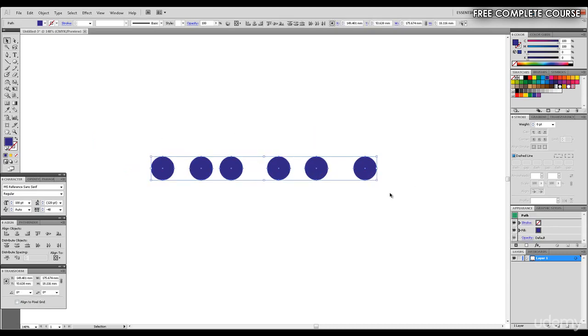And I'm going to highlight all circles, and I'm going to click on this icon beneath Align Objects. Clicking upon that, you'll see that all of the circles have been aligned one on top of another to the left. If we undo that with Control and Z, back to the original state, I can show you the next,